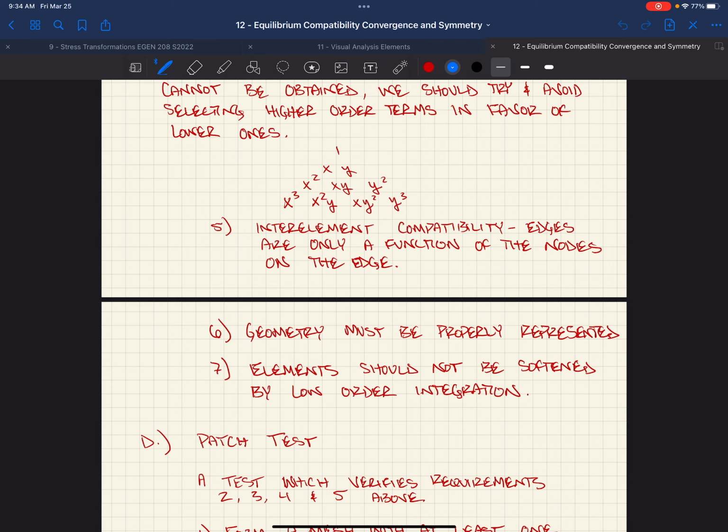So you're refining your mesh, but at an elemental size? I guess so. You're essentially losing contributions that are actually there. I feel like it could go either way, you could lose stiffness or gain stiffness. Right, it's just the way it varies. Yeah, I don't think so. No? It's like an extra way to displace, right? Yeah, like an extra mode shape. So you're essentially losing a contribution, so it's always going to change the displacement in the opposite direction. You're pulling back, it's going to make it stiffer, I guess. I can't really think of a better word.